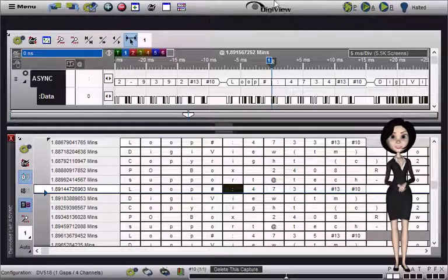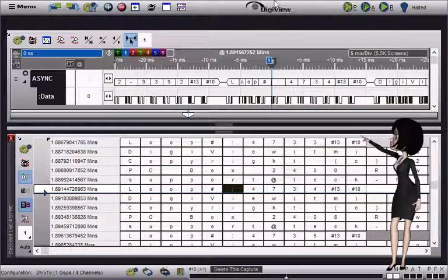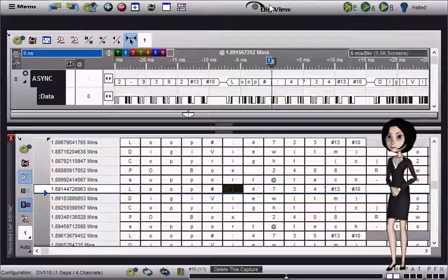Use the asynchronous signal type to see a single channel decoded and displayed as serial characters, or frames of characters with a specific bit count and baud rate. We have already added an asynchronous signal to our project and captured some data. Let's open the Signals editor to see its configuration options. Click on the signal name to open the editor.